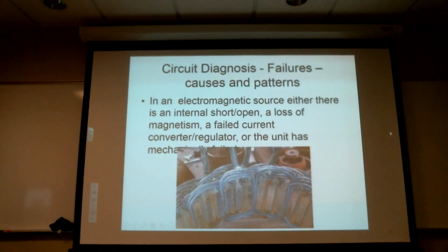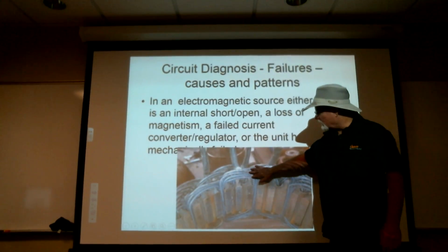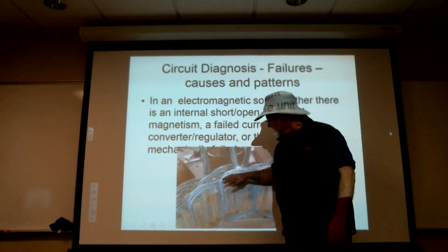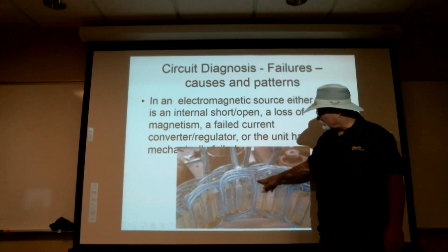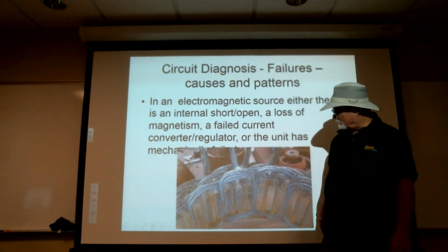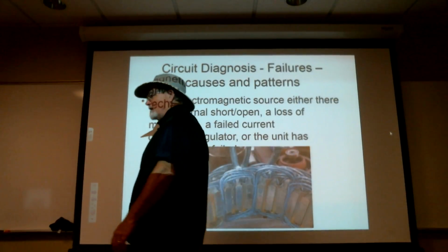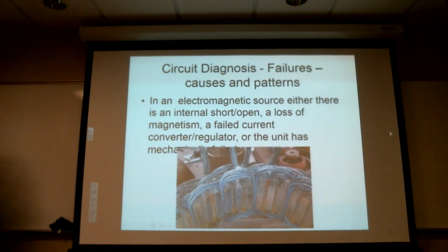This one looks like, given that all the windings are pretty well toasted, but the interior windings look like they got the hottest. These look less damaged. So this interior winding shorted, and you can see the insulation is completely baked off of this. So that as a power source, and by the way, that can also be an electric motor, to do the same thing.